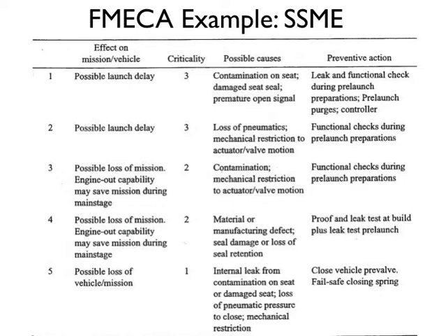So if you can imagine, again, a missile that's sat in a silo for 10 years and is then going to be launched, a lot of the probability of occurrence of that failure mode will be due to that 10-year period where it's sitting through these diurnal temperature, humidity, pressure, vibration cycles. And if that particular failure mode in some form or fashion can be checked on right before launch, it can actually eliminate a lot of the risk. So that's good to note.